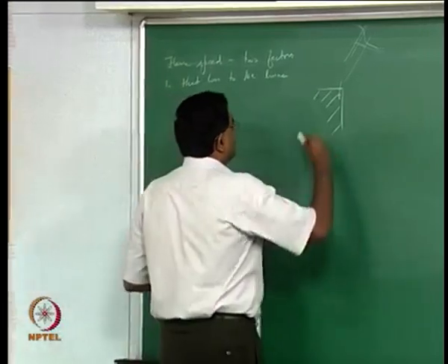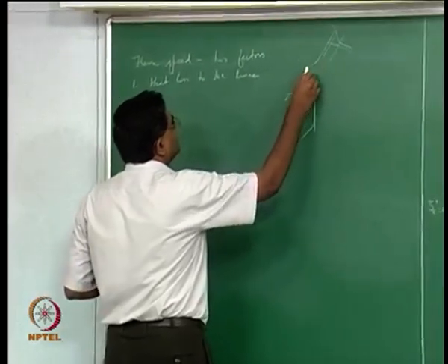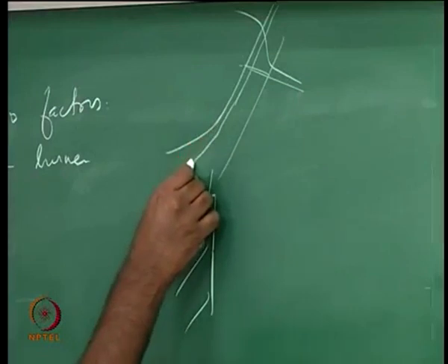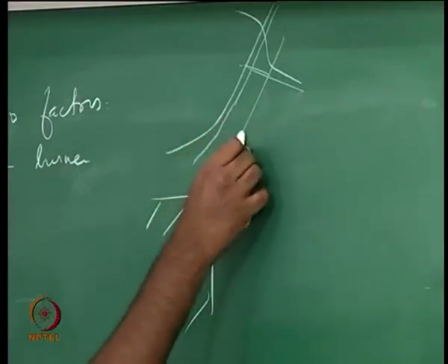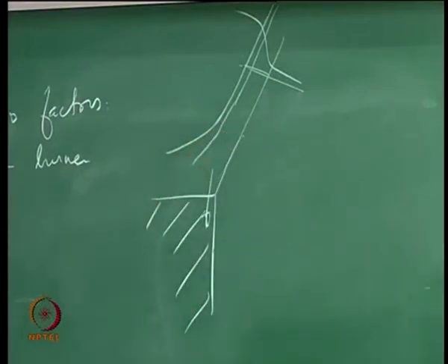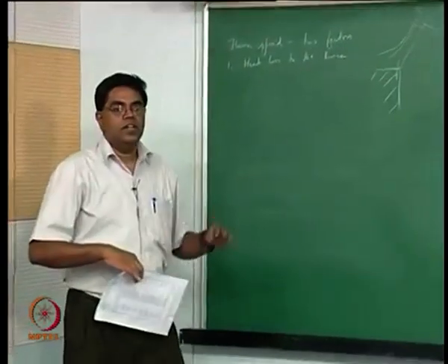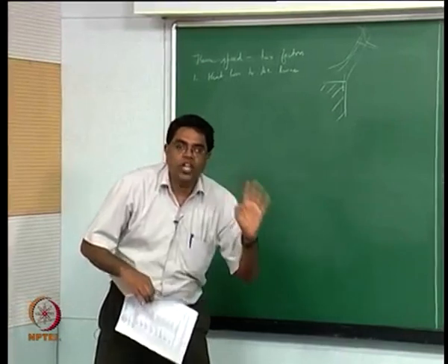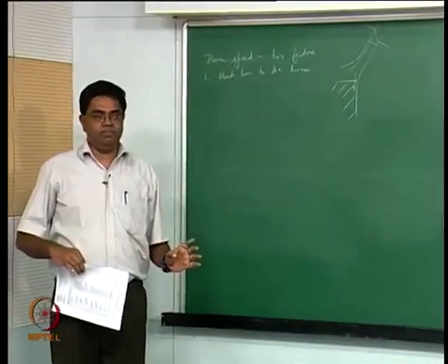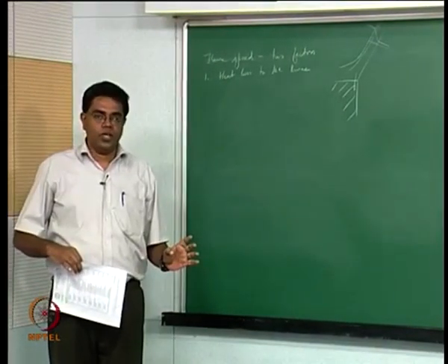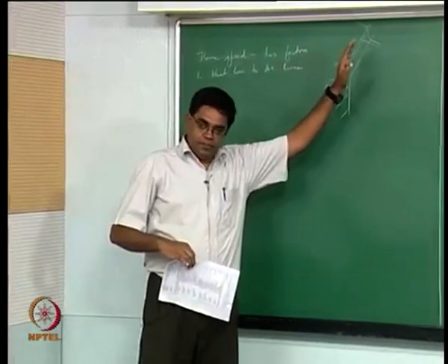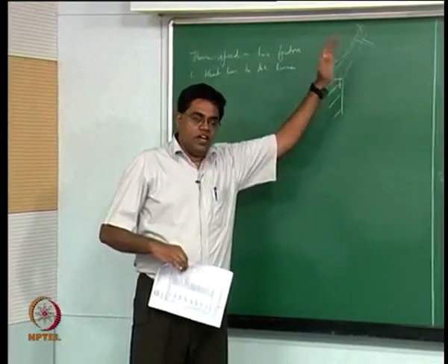So what then happens is, you now essentially are thinking about a progressively thickening preheat zone, and the fact that we are talking about a heat loss is because the reactants are not the only ones that are getting heated up. Okay, in an adiabatic flame there is a heat transfer going on.